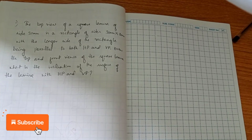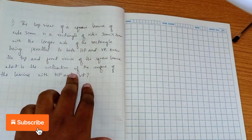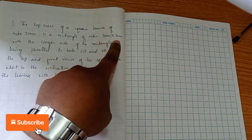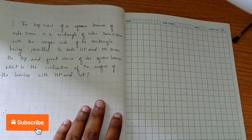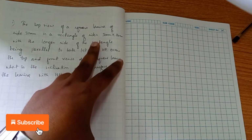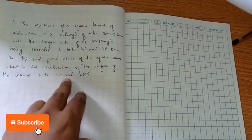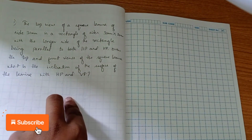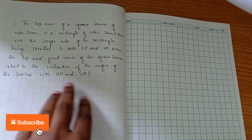Today we are going to learn another type of problems on rectangles. You see in this problem the top view of a square lamina of side 30 mm is a rectangle of side 30 into 20 mm. So it's like your isosceles triangular problem, wherein first we have to construct a square of dimension 30, and your second diagram will be a rectangle. After that, we proceed with the longer side of the rectangle being parallel to both HP and VP. In this problem, they have not mentioned any kind of inclinations to HP or VP. So based on the question given, we have to do it.